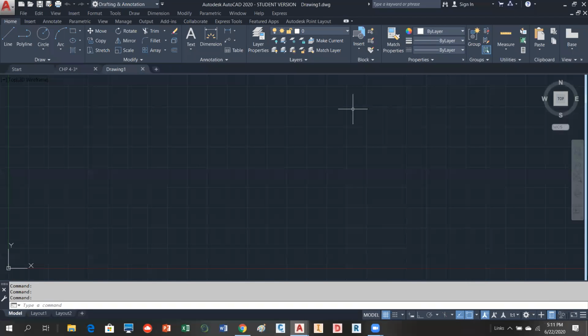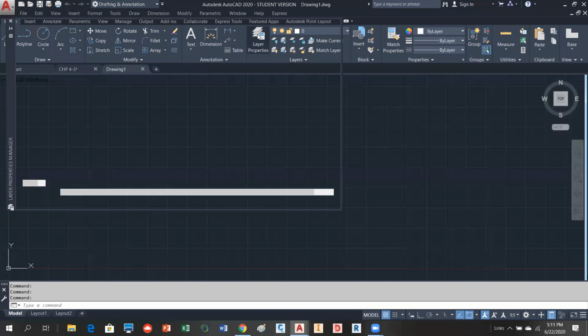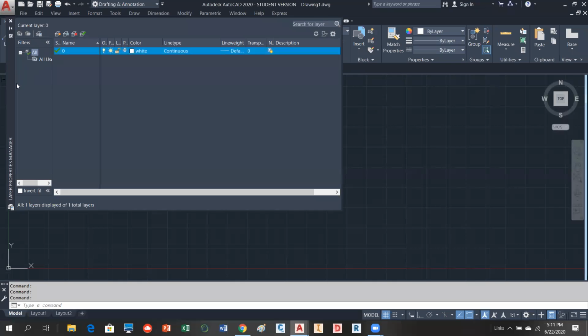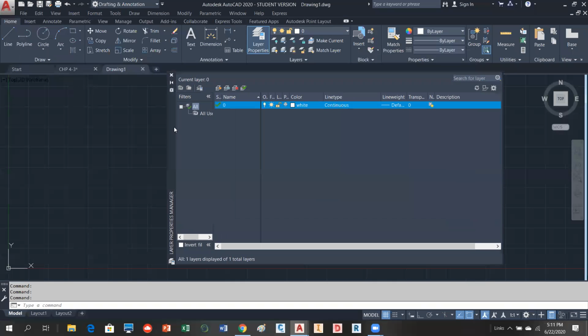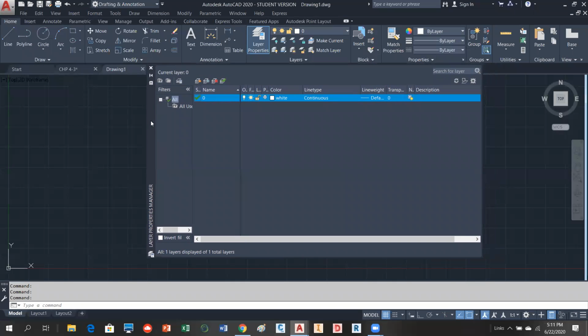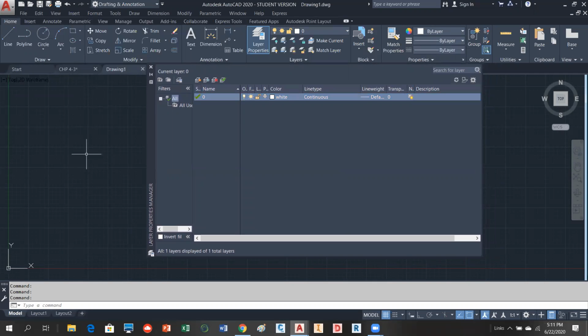Okay. So we're going to go to the layer command. If you were typing it in, you could just type in the word layer, L-A-Y-E-R, or its alias, which is L-A. Having the Home tab open right here, this is your layers command. It's called the Layer Properties Manager, but we're going to go ahead and open that up. You should see this dialog box that will float out, and it's movable. Okay, so if you want to go ahead and open that up, let's get that. Okay.